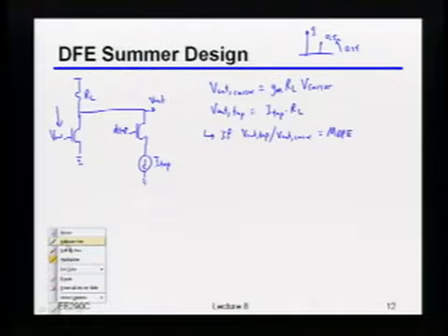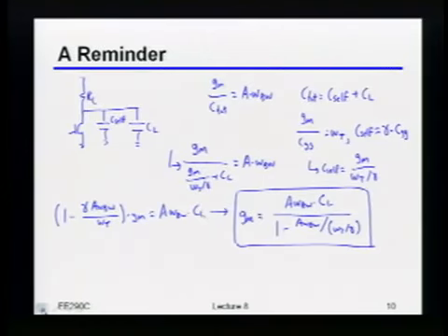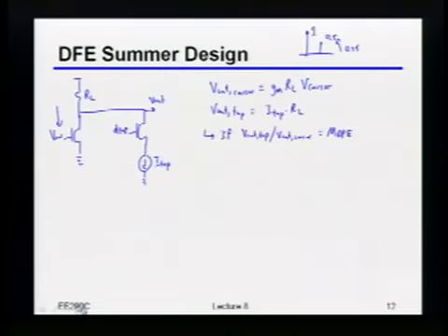So we're trying to calculate what that approximate loading cap will be? What we're going to do now is, just like two slides ago we calculated what the GM needs to be as a function of where you're operating relative to the gain bandwidth. Now, as a function of this MDFE, I'm also going to calculate what the GM actually has to be. In fact, I'll recast it so that it'll be more directly in terms of what bit rate you're operating at, what the digital delay is, and things like that. You'll see it'll be slightly complicated, but it'll be a one-line expression.